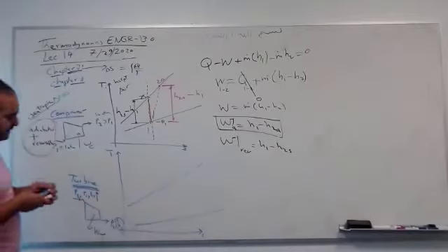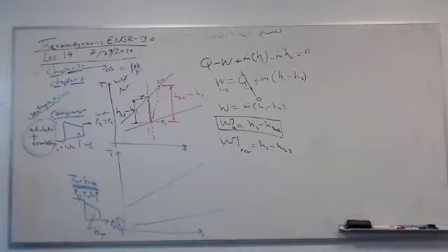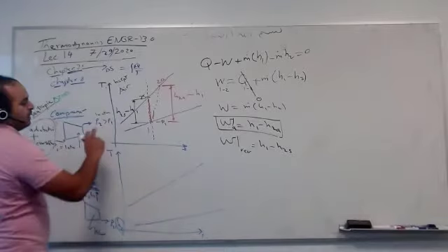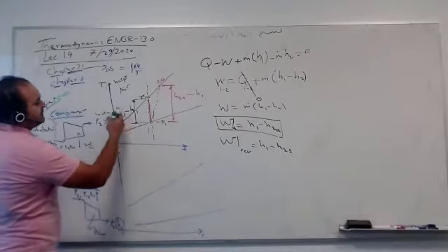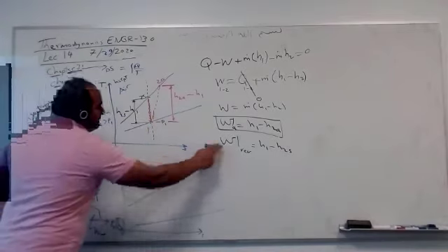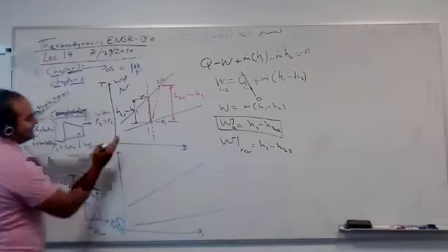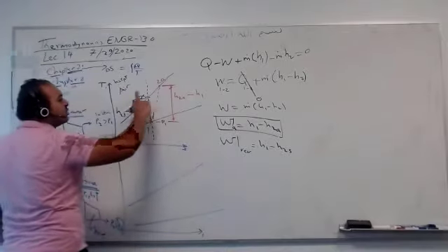So this vertical distance, guys, if I am adiabatic and reversible, we call it 2S. So H2S, and the work is negative, so it's H1 minus H2S, which is this one. Very, very reversible, you mean ideal. It's very isentropic. There are no losses. But in reality, we have losses, so it is slanted like this. So this distance is shorter than this.